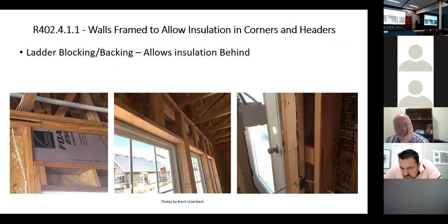And that really should have another piece of foam or something in it so it comes right out to the drywall. But this is much better, the foam in that header, than nothing. Usually nothing goes in that space, you know, the extra space. Lots of times they put a filler inside.